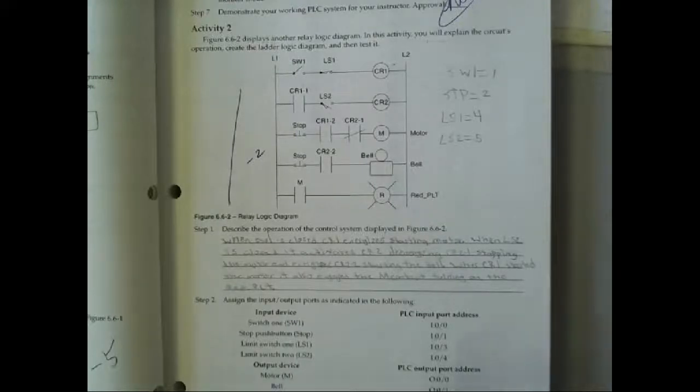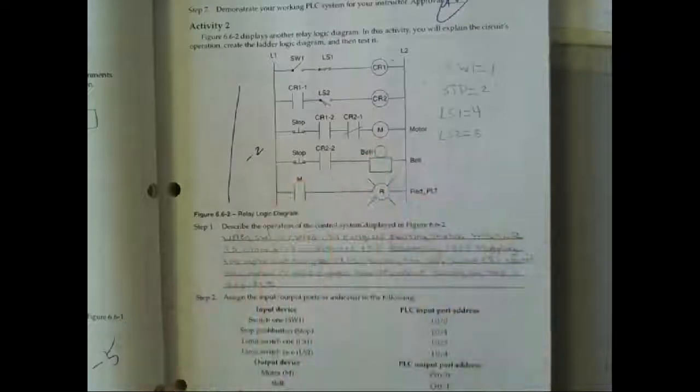Now the 1000 is a fixed PLC. What that means is you get what you pay for. The 1100 is a hybrid PLC. It comes with some fixed inputs and outputs, but we can add additional modules to that. What's nice about the 1100 is that if you run out of B3s, you can make another B file. I'll show you how to do that on that PLC. You can make a B10, because we're already using up to 8. You can make a B11, so you could have a lot of contacts on a PLC that's not fixed.